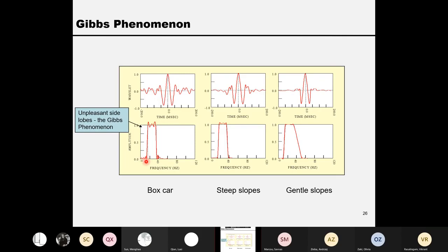The second important principle is the filter spectrum should be smooth. Here on top, that's not smooth. You can have some frequencies after filtering that are amplified because you multiply by a coefficient more than 1, like 1 point something. Some frequency components are suppressed a little bit. So ideally, the top bit should be 1, so the most flat field.